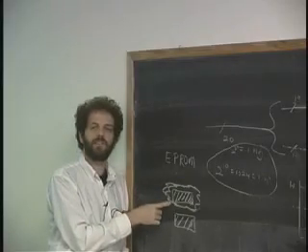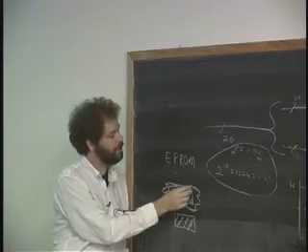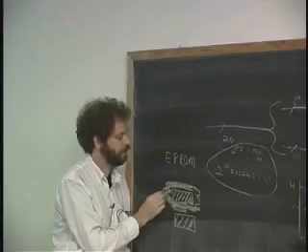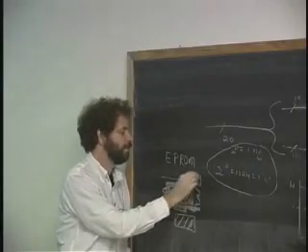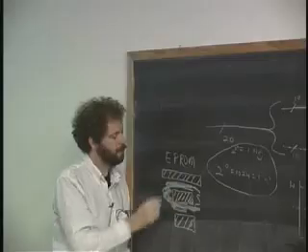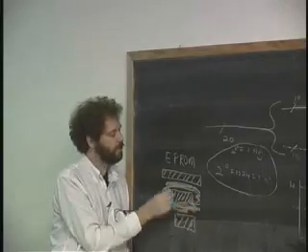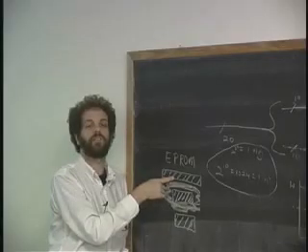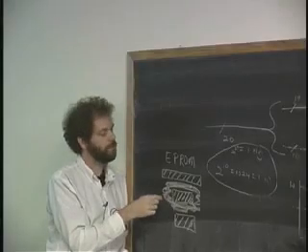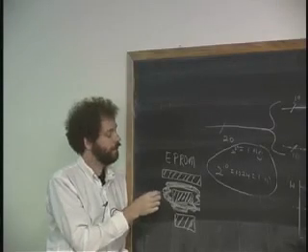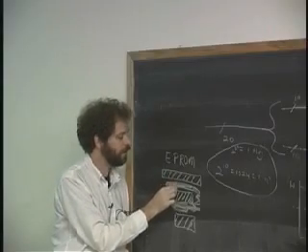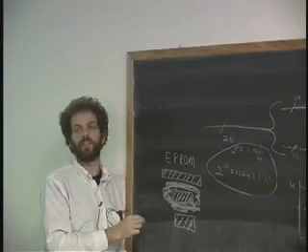So how do you store energy in here to begin with? Well, it turns out the glass is an amazing thing. It has a characteristic of two things. First of all, you put another plate on here of semiconductor. So this is really 3 plates, like so. And even though there's glass here, if you put enough voltage on this guy, like 20 volts, most of these things run at 5 volts, but if you put 20 volts, due to a process in physics called tunneling, some of the electrons here are so hot to get to the other side that they will squirm their way through the insulator and get to it anyway. Okay? But you need a lot of volts here.